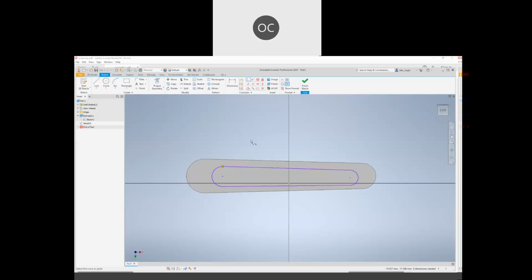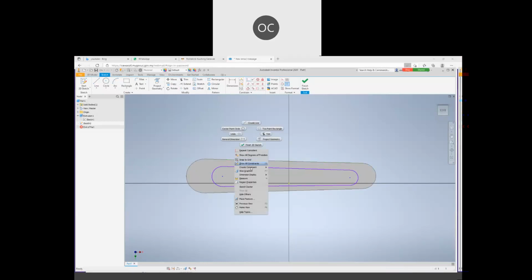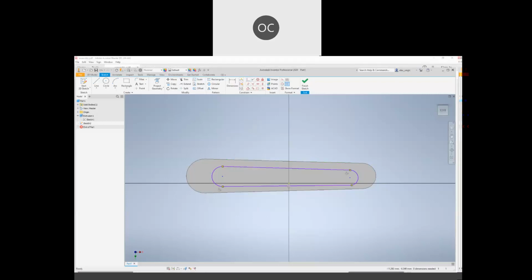So we continue on that. It will be almost similar steps to the previous one. So right click first to show all the constraints and ensure that you have them. Okay, then the first thing that you need to check will be the tangent constraint, of course. So at this point, I don't have the tangent, so I apply the tangent constraint similarly to these two.